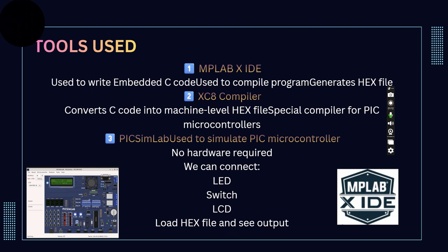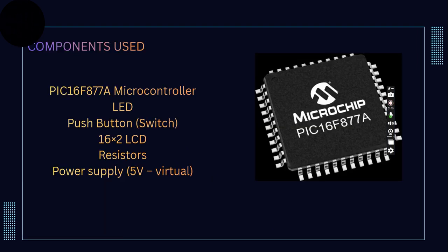The main component is the PIC 16F877A microcontroller. It is an 8-bit microcontroller with multiple digital input and output pins, built-in timers and peripherals like ADC, which makes it very popular for academic and beginner embedded system projects. In this project, the PIC 16F877A acts as the brain. It reads the input from the push button switch and controls both the LED and the LCD according to the program stored in its memory.